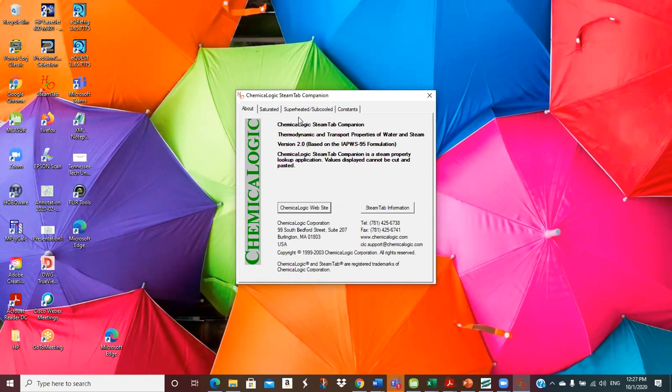Oh wow, that's 2.23 million BTUs an hour. So I divide by 1,000,000 to get it in millions. Yeah, 2.231 million BTUs an hour. And if we put that heat directly in a fluid that we were going to heat with some sort of a heating device, say using natural gas, that heater would probably have an efficiency of 80%, is kind of a standard number.